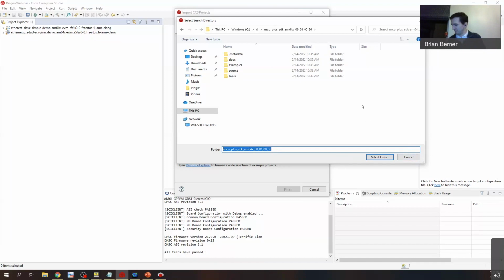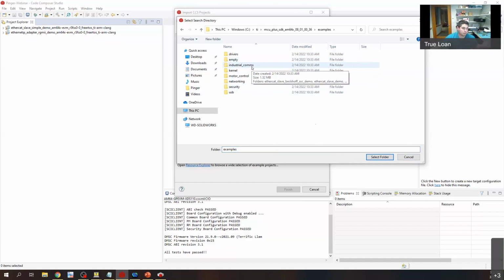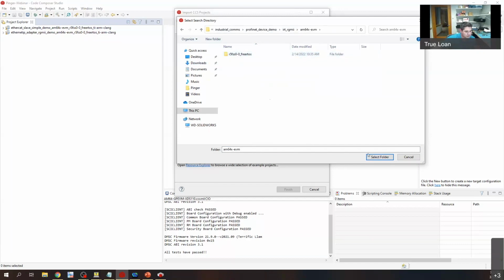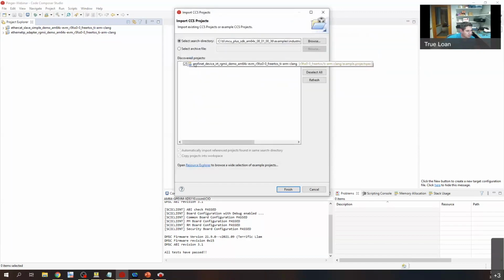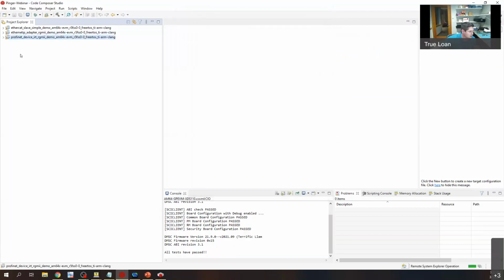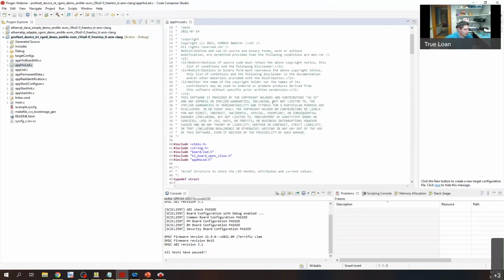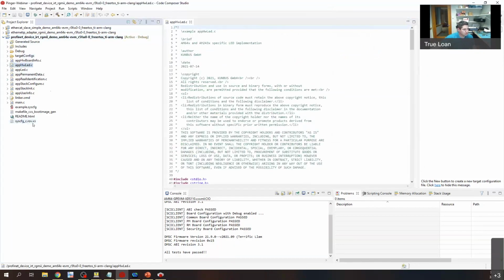Okay, thanks, Brian. I'm going to keep diving in here. Just to recap, we're taking Code Composer Studio and we're going to install the default Profinet example. So I'm going to examples, industrial comms, Profinet. There is documentation from TI on how to install the MCU Plus SDK, so I'm not going to show that part. I'm just going to install this example. We're going to select that directory. The project itself isn't going to be visible. Once we have this example here, we can take a look at the code if we wanted. We're going to see that this is actually a FreeRTOS example.